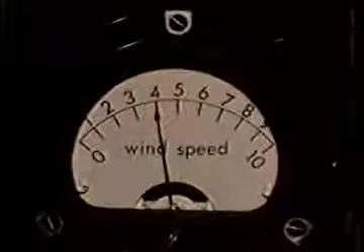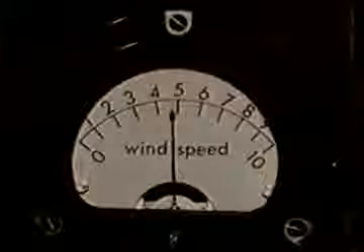We can control the airspeed and we can put disturbances into the fluid. At zero airspeed, a disturbance damps out quickly. At low airspeed, it still damps out. At this higher airspeed, if we put in a disturbance, waves appear and grow. At even higher airspeed, waves seem to appear spontaneously and grow. The flow is unstable.